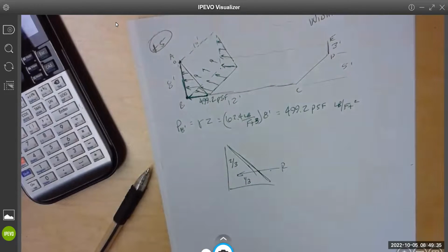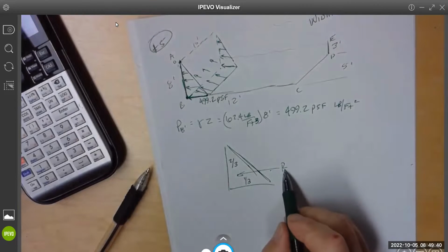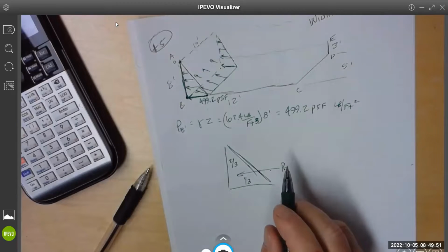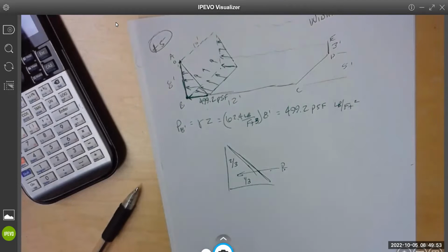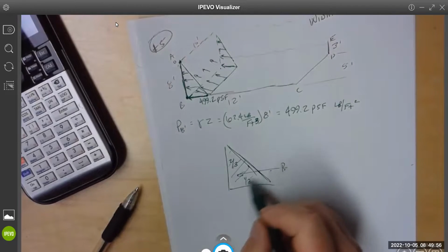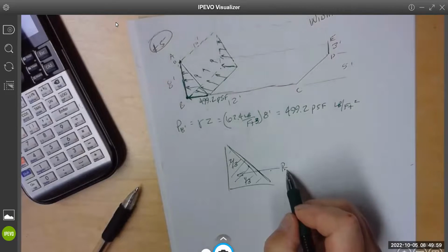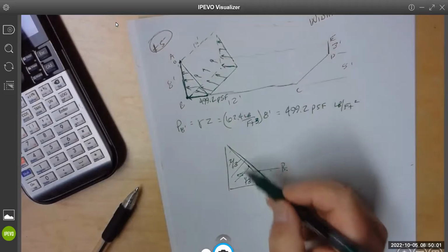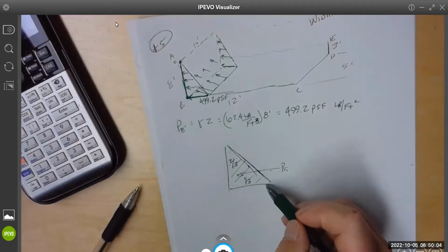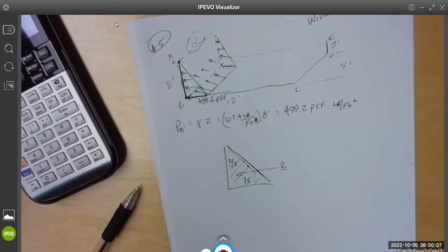How do we get the magnitude, like how strong it is? Well, we would find the area of the load curve. This area is how we get that. Since it's not just an area, it's a volume, we would find the area and then multiply it by the 10 to get the entire length. So it's just calculating a volume of the load curve.